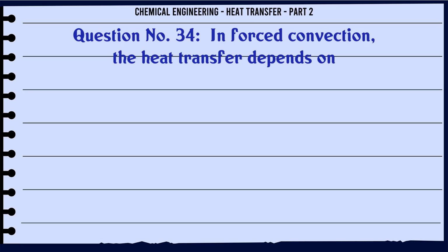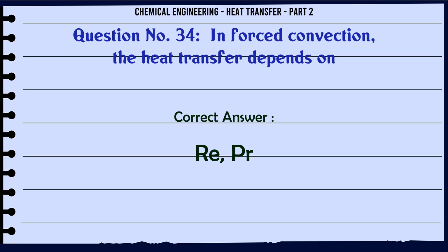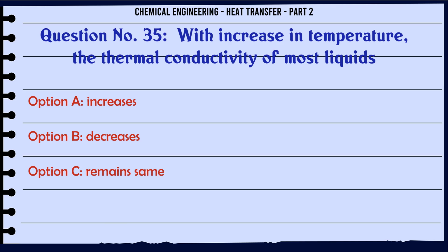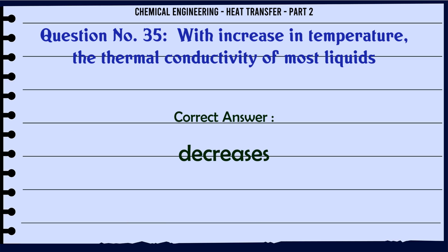In forced convection, the heat transfer depends on: A. Re-Pr, B. Re-Gr, C. Mainly Gr, D. Re only. The correct answer is Re-Pr. With increase in temperature, the thermal conductivity of most liquids: A. increases, B. decreases, C. remains same, D. first increases up to a certain temperature and then becomes constant. The correct answer is decreases.